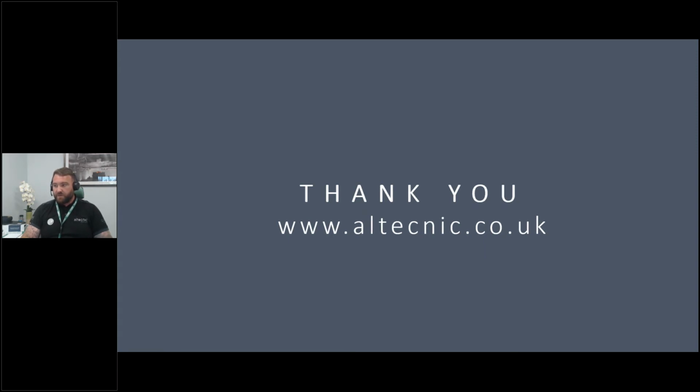Great. And then there's just one last question, Ed. Are you able to link a HIU to an unvented cylinder? Well, you've got to remember, we have to generate pressure. So we have what's called a ProSol unit. If someone wants to store hot water, we can connect a HIU directly to a cylinder, and we can take the hot water production from the HIU and put it into a cylinder, essentially. So you can connect them, and we do it on the market. There is one called a ProSol unit.